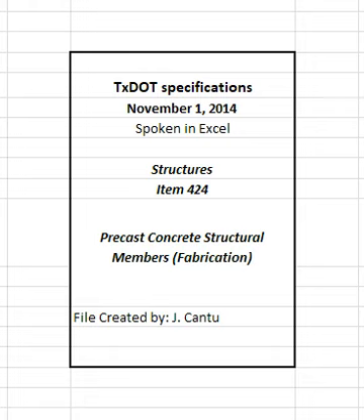4.2.6 Finishing of concrete. Finished, unformed surfaces must not have distortions greater than 1/4 inch. Screed or rough float unformed surfaces of members, bringing enough mortar to the surface to embed and cover the coarse aggregate. Provide a uniform rough wood float finish to the surface of the member unless otherwise shown on the plans. Do not loosen aggregate when roughening the surface with a broom or when providing a tine finish. Provide a smooth metal trowel finish for surfaces at anchor bolt locations.